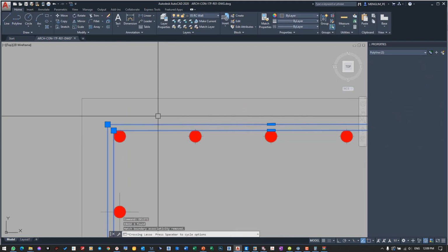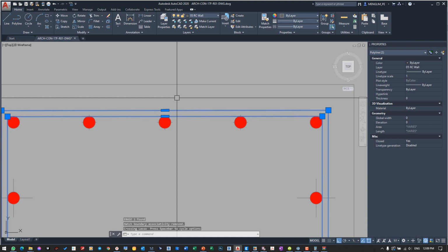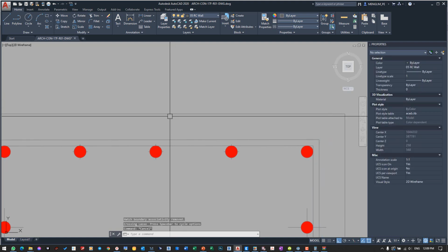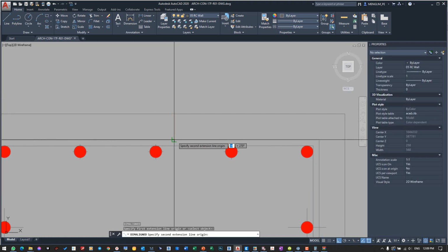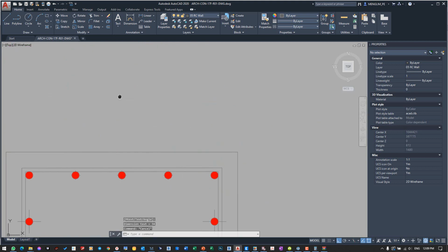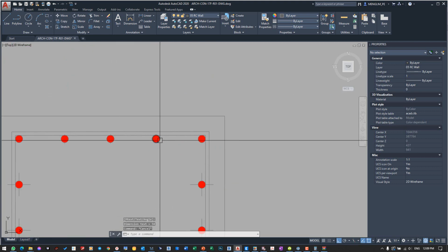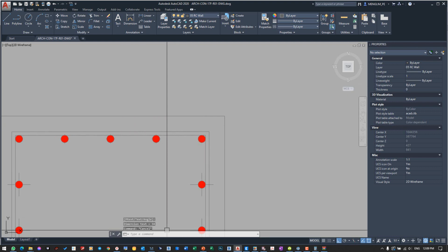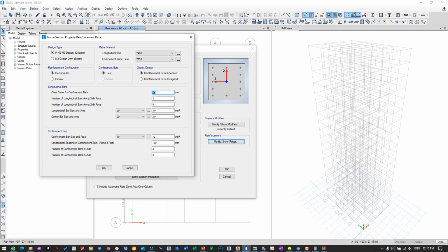This line should be the stirrup. So we can assume that the cover of the column from the surface of the column, we take about 30 millimeter clear space for the cover. So I will put here about 30, and click over to, and the program will count to the center of the bar. So h divided by 2 is 4, so it's 35. You can find the 35.